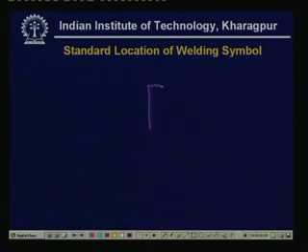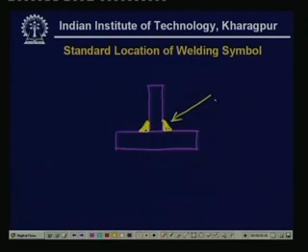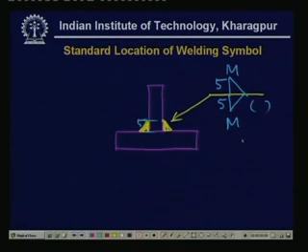Suppose we have two parts which are welded this way. Now if the arrow points that way, that is the point. So if you want to use this weld, then we will have to write the proper welding symbol on both sides. Let us say 5 millimeter. If the 5 millimeter is this height, then 5 and 5, and then it is to be machine finished. It's a straight edge. So all the information is given, and maybe you can apply the length.